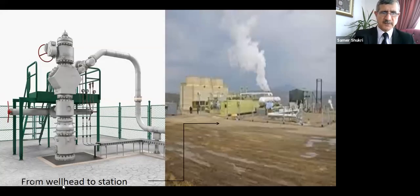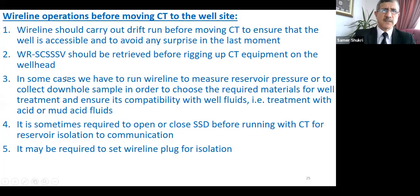Here also the well will flow from here to the station. The station is here. We separate oil from gas and water. The gas is sent to the gas plant. The water is re-injected again into the well, and the oil is treated and produced or exported.